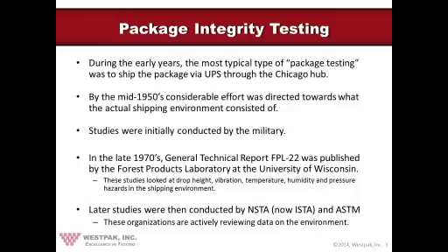Resulting from this effort was a series of papers and articles that, when taken in total, offered a pretty good quantification of the distribution environment hazards. Specifically, impact levels were quantified in terms of drop height as a function of package weight, orientation of impacts, and total number of impacts. Vibration levels in vehicles were quantified in terms of their input spectra, duration, and overall intensity.